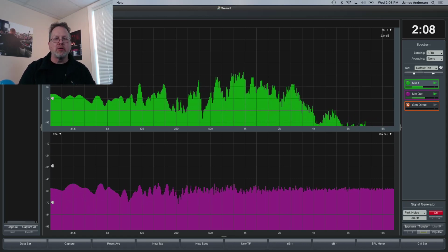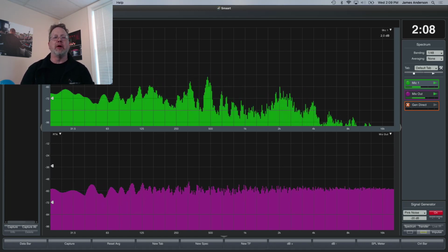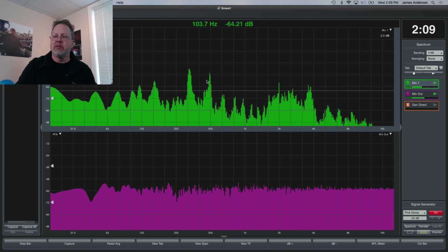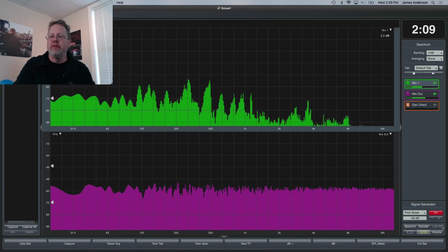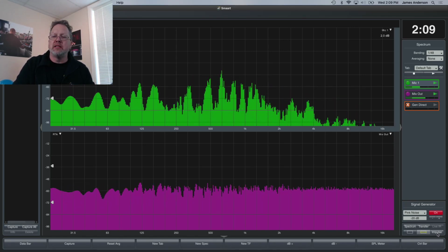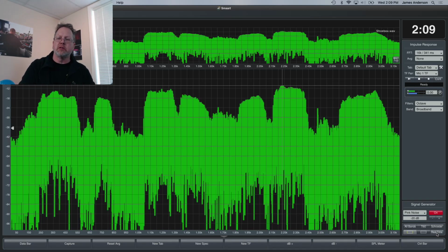If I is one of the hotkeys you hit, you end up in a mode like, where'd my data bar go? The other way you can get there is by coming down into the lower right-hand corner, in the little view section of the command bar. It says impulse right there. And of course, when I hit that button and take us to impulse response mode, that button turns to real time. That's the take-me-back-to-real-time-mode button.